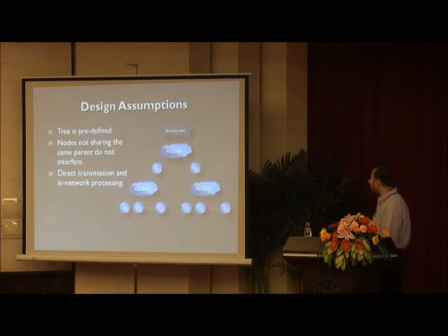So in this work, we consider three levels. And let me explain here, there are two phases in this problem. The first phase is carrying out the optimization algorithm to specify which sensors will contribute and what are the communication parameters. This is usually done at the beginning by the decision unit asking sensors to transmit their parameters about a specific resolution cell. Then this information is propagated back either at the decision unit or at parent nodes. The optimization problem is solved, and then the design variables are propagated back to the sensor nodes. Now, every sensor knows for each resolution cell whether it is going to contribute to the detection process or not, and what are the communication parameters that it will use.